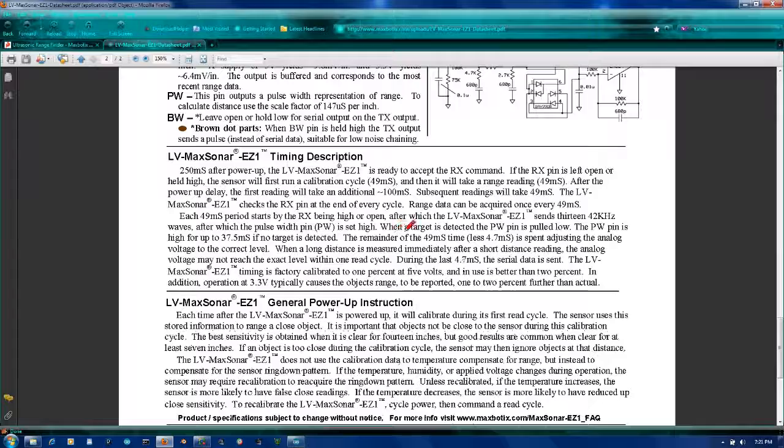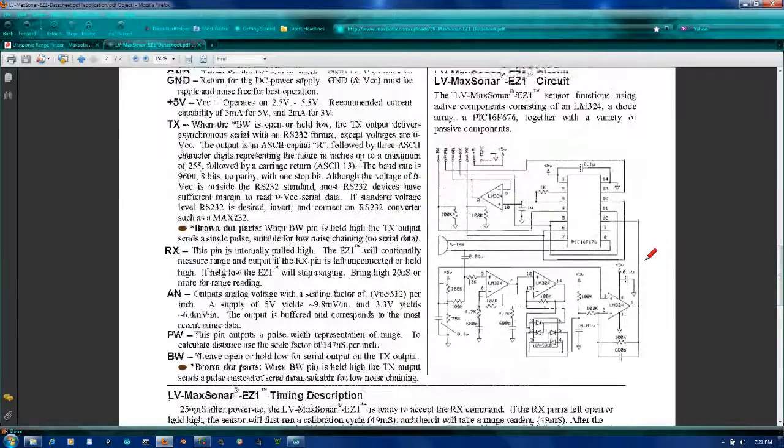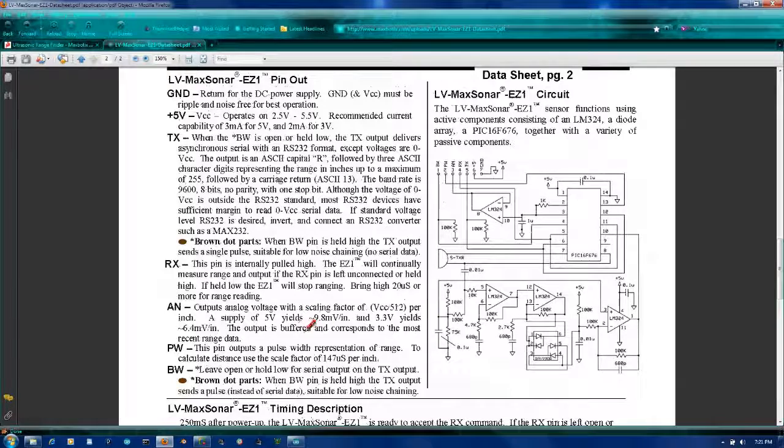It would be a straight line going down. So it's 9.8 millivolts per inch, and it goes, you know, for 250, we'll call it 250 inches. And so that would be a linear graph. So when we map this one out, we will get an even distance in between all the lights if we keep the same number.